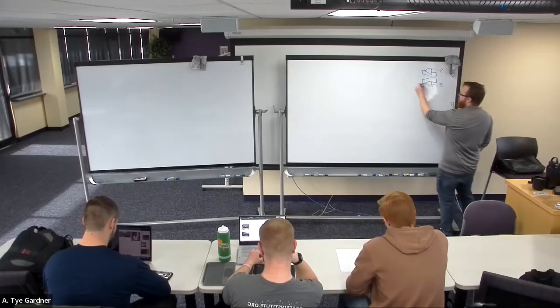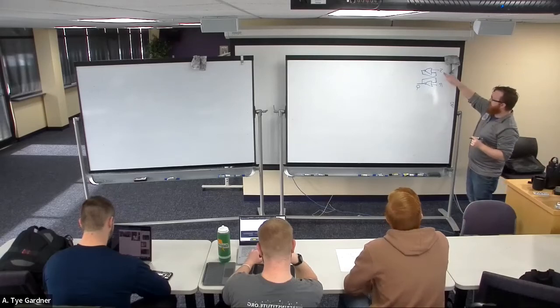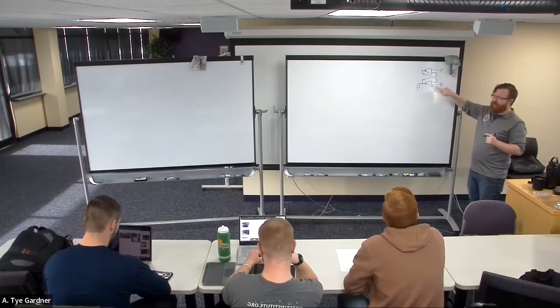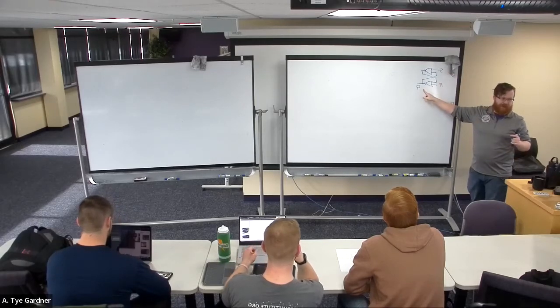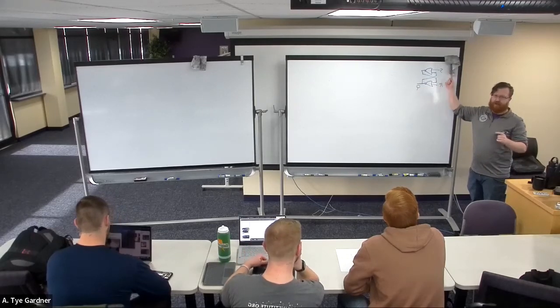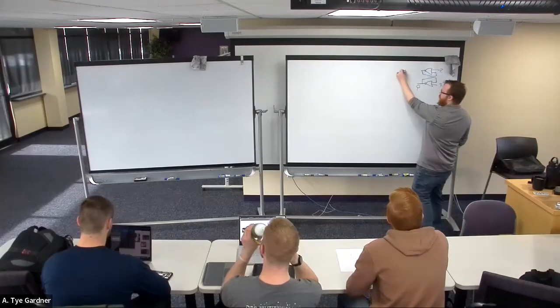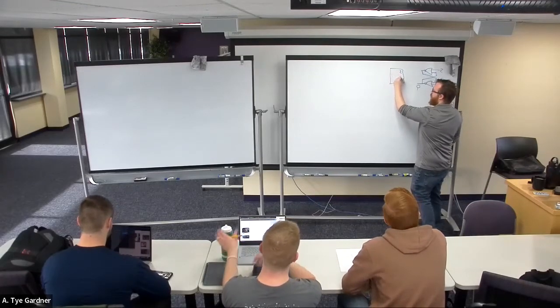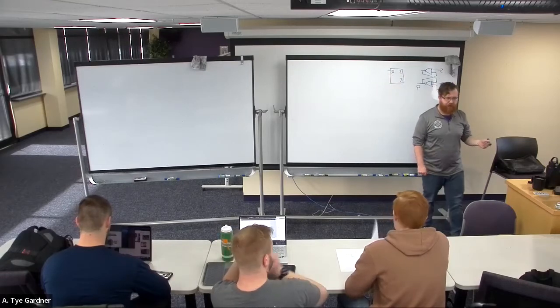And this we called Q, because if I set the value, Q will become 1. If I reset, Q will become 0. If they're both 0, Q will just stay whatever it used to be. And if I assert both, I break the circuit and unpredictable behavior happens. Then we wrote the symbol. And now we have an SR latch.